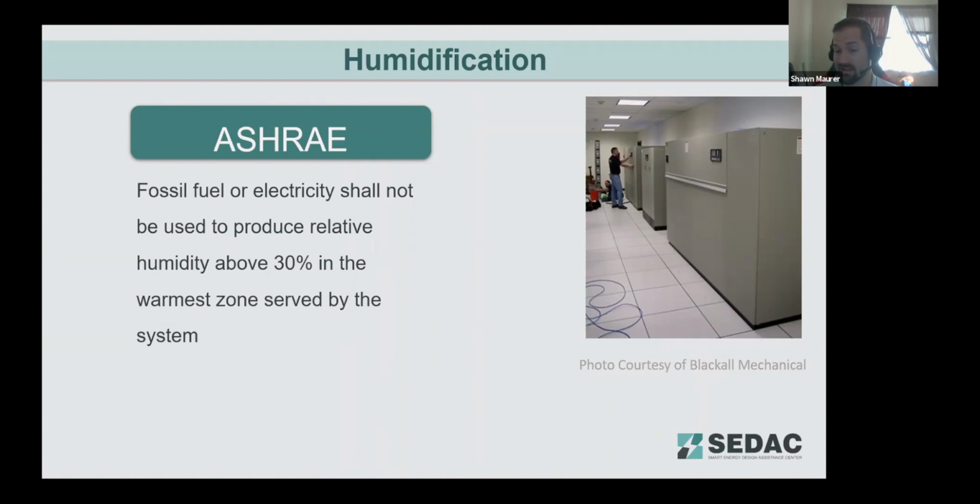The other thing we're looking at is providing adequate safety against the risk of static discharges in facilities, particularly where you've got electronics. And that's where the allowances come in for specialty situations, such as archives and other preservation methods. There are exceptions for those where the relative humidity might need to be a little bit higher than 30%. Those exceptions are included in ASHRAE.